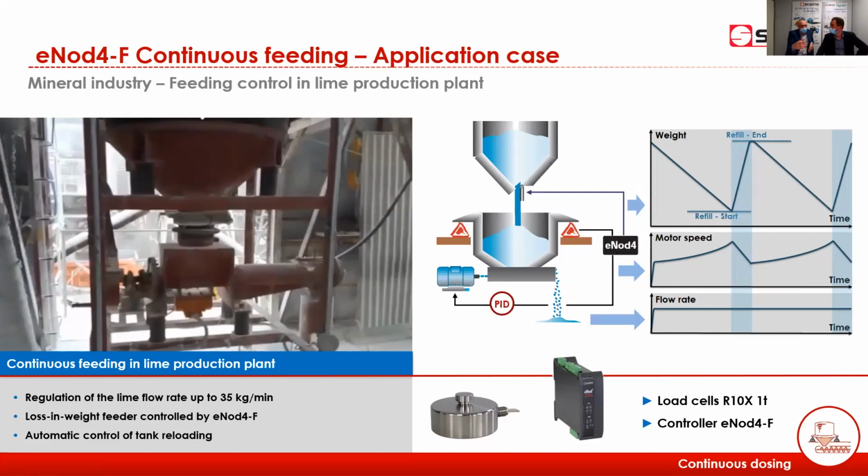We have a smart refilling mode where the eNod4F takes in charge the calculation of the value that should be used, or you could use a fixed value, and you could use the last value of a different mode depending on the applications.